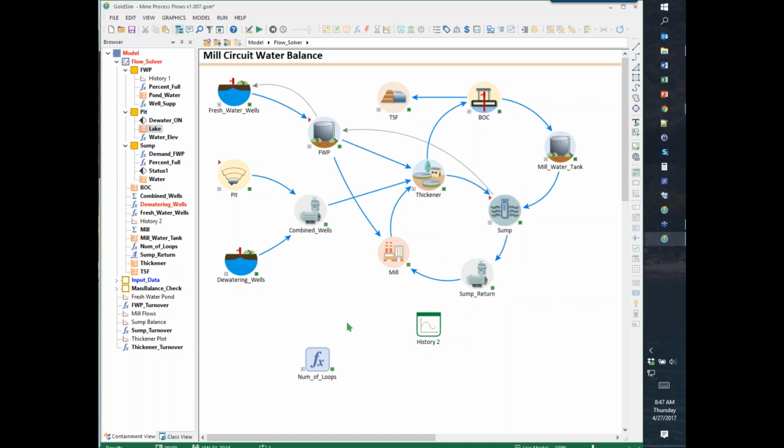Another important point found in this model is that, in reality, the way the thickener works is there's a rim all the way around the clarifier, a weir, and water flows over this weir around the edges. And so the way we started building this model was to simulate a weir at the clarifier and say that, based on the depth of water over this weir, we're going to calculate a flow, and that's all fine.